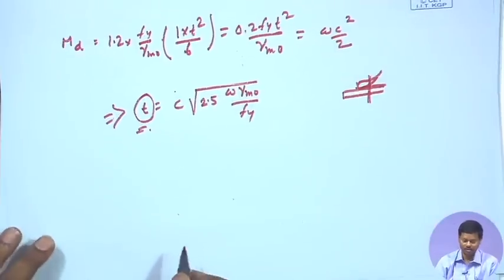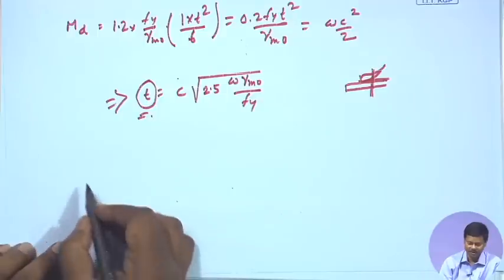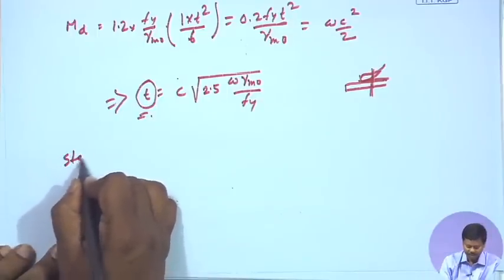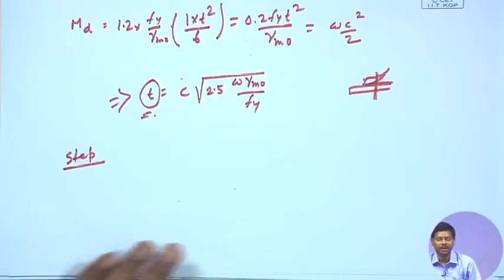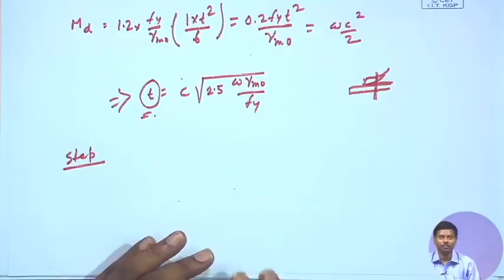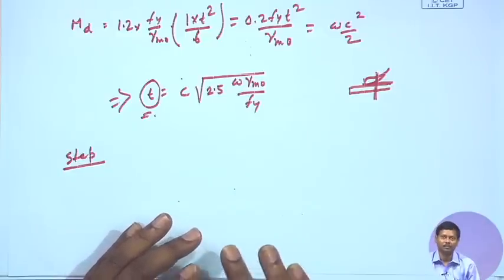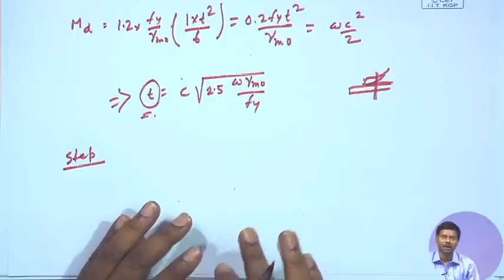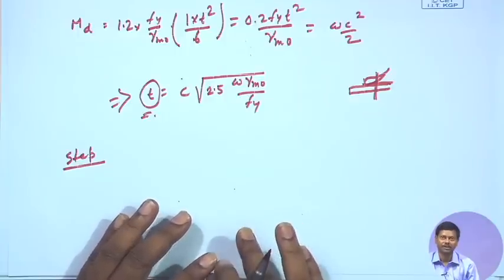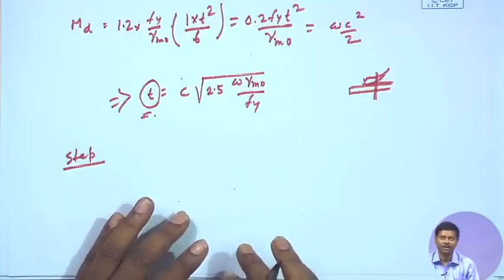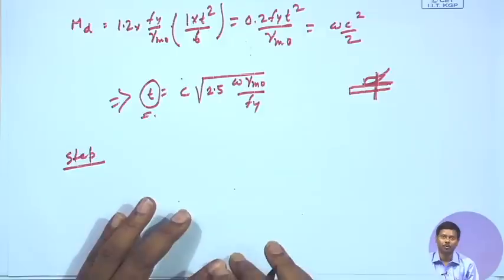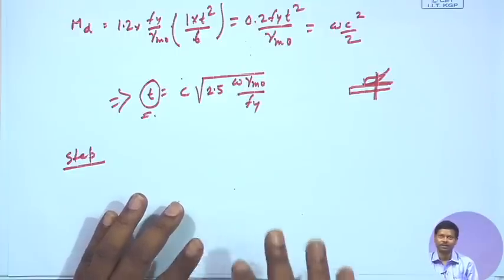Now, we will go for design of the Gusset base. So, step by step we will try to find out how to design a Gusset base. So, designing a Gusset base means we have to design the base plate. Base plate means the dimension of the bases, which includes thickness, length and breadth, and once it is decided, then we have to decide what will be the number of bolts required for the connection of the Gusset plate with the column sections. This is one we will do.